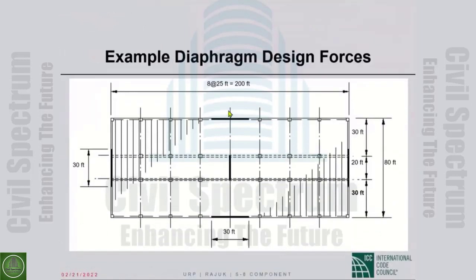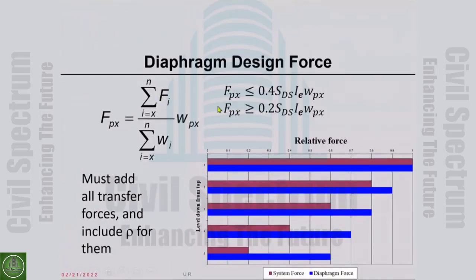The diaphragm design force also has a lower bound on it below which you shall not go. The lower bound is mandatory, the upper bound is up to you.